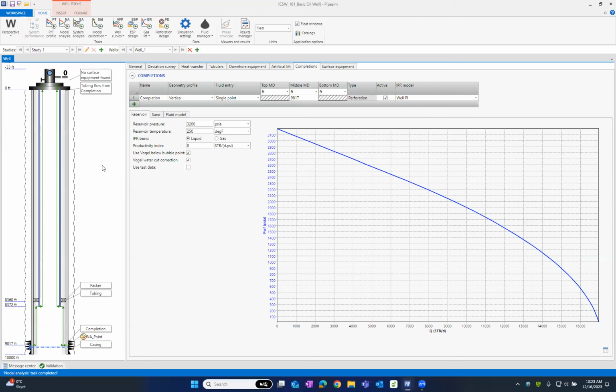The pump is mechanical equipment that uses electricity in order to push the fluid inside the wellbore and play with the VLP curve. The most common design, because it can cover a very wide range of operating conditions and flow rates, is the electric submersible pump, the ESP.